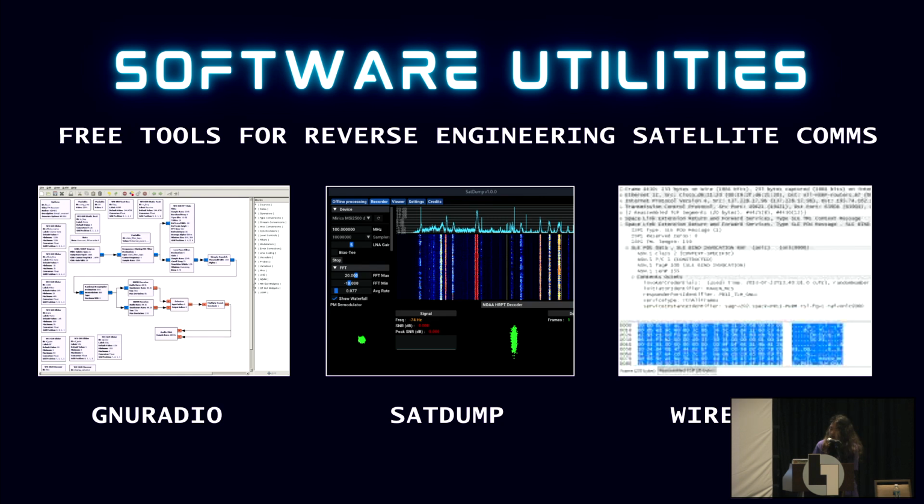And then Wireshark. Once you have a consolidated PCAP of packets, once you get through the demodulation phase and you get a sequence of packets together, then you can go through packet dissection and reverse engineering each of the independent packets and associating it with either the CCSDS protocol or its own proprietary reverse engineered protocol in order to get your encoded data output.